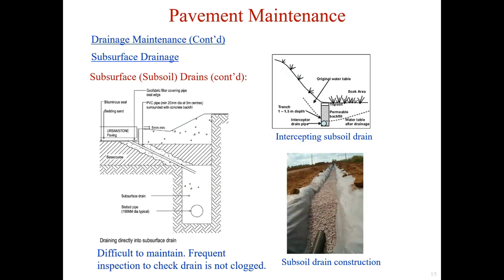It is difficult to maintain the subsoil drain. Frequent inspection to check that the drain is not clogged is needed. If necessary, drains should be dug out and relaid using a properly designed filter material.